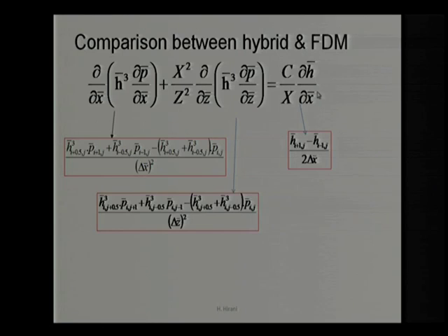Now, many times what happens? Many times h is given as a film thickness, and this expression can be directly figured out. In that situation, we do not really have to use a finite difference method. Assume that we know already h as 2 by 3 and bracket 2 minus x bar. We can simply differentiate, we do not have any complexity in that differentiation.